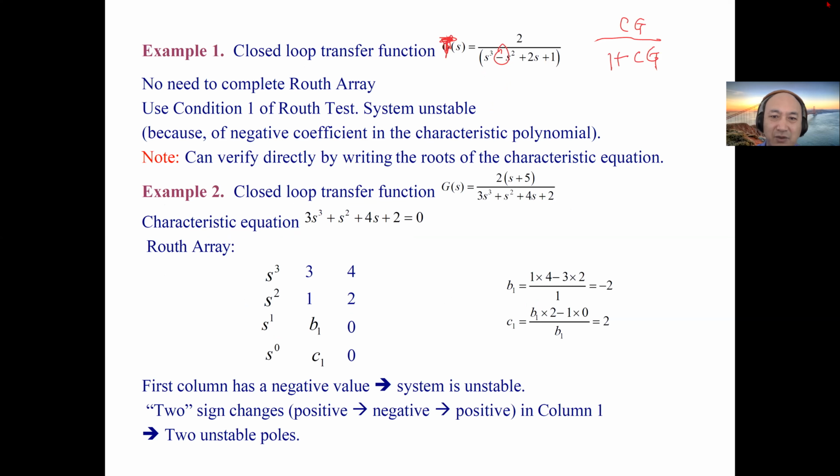So this is a closed loop transfer function, and this is called the characteristic polynomial. You usually need to solve its roots, but it's very difficult to do by hand, solving the roots of a cubic, a third order polynomial. You can do quadratic, but not third. It's difficult. So what you should do is, this is a_n. a_n minus 2 is this one. Let's skip this one.